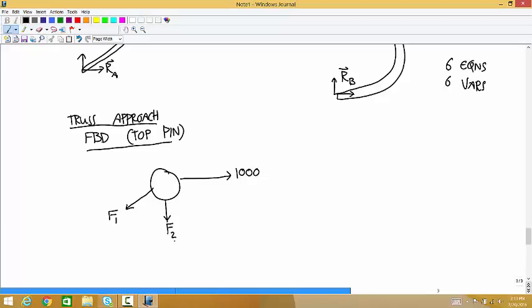With two-force bodies, you know that those forces are equal and opposite, and parallel to the line between the two joints. So no matter what this body is doing in between those two joints, that force has to point to the bottom joint. And then you can just solve it like this. Yep, 2 variables, 2 equations.